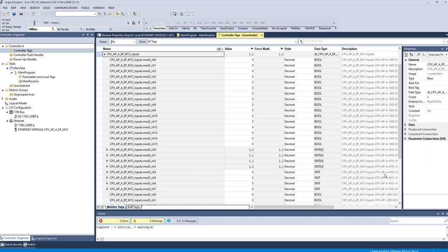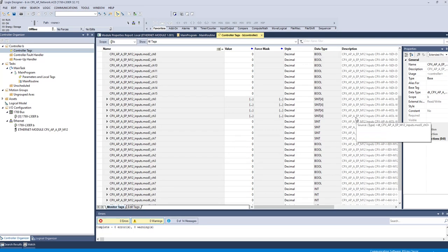Then we move down to the next item here, which is still part of that I/O link module. This is status type data for it. And then we step out to the AP-I. Now we go to the decentralized, because the last module on the AP-A manifold was an output module, so that doesn't, of course, show up on the input side.